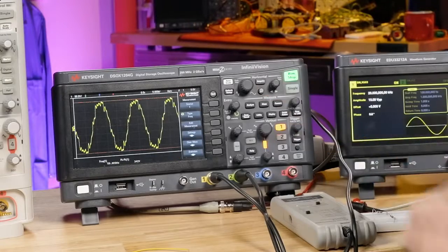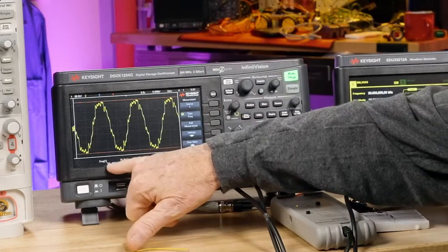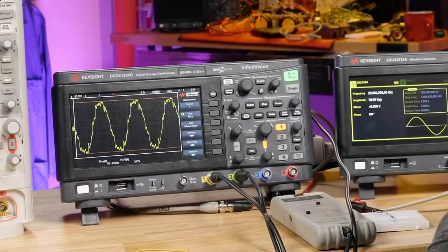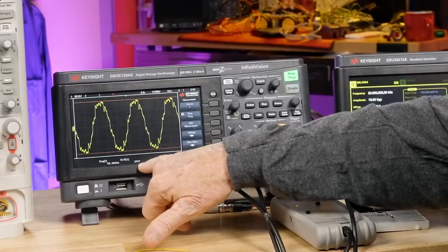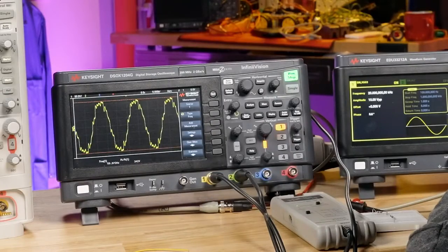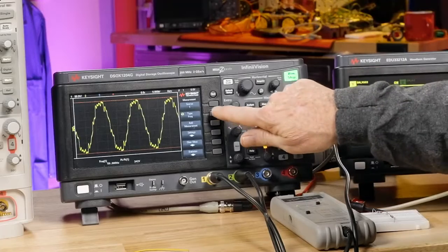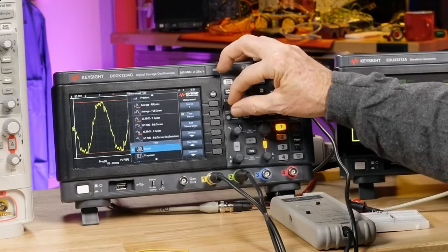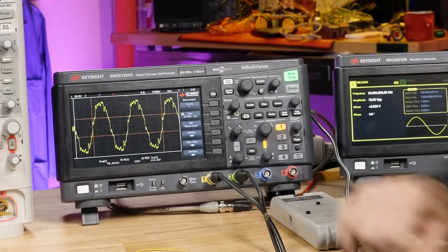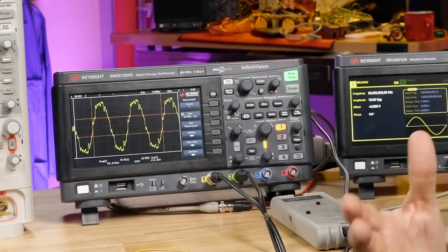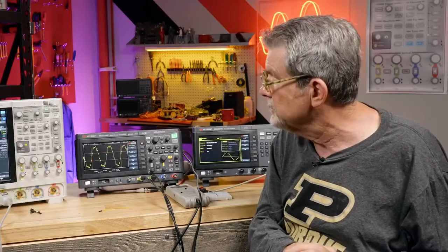So I'll select measure. The two default measurements pop up. It says 60 hertz. That's what the frequency is here in the US. In Europe, it'd probably say 50 hertz, similar in Asia. The peak-to-peak voltage, it says 340 volts. Now you're thinking, in the US, don't they have 115, 120? That's RMS. So let's select an RMS measurement, and it measures about 120 volts, pretty much what we would expect.